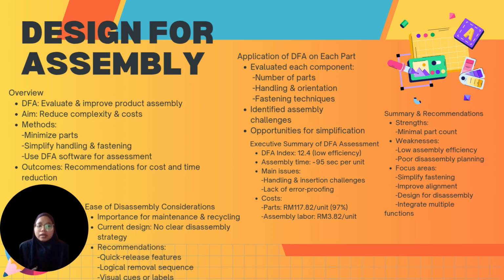The DFA results show a low efficiency score with a DFA index of 12.4 and an assembly time of about 95 seconds per unit. Most of the cost, around 97%, comes from the parts rather than labor, but improving assembly could still reduce error and save time.